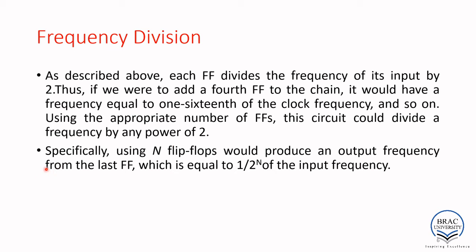Specifically, using n flip-flops, it will produce an output frequency from the last flip-flop equal to 1 over 2 to the power n of the input frequency. Okay, so input frequency divided by 2 to the power n. So it will give you the divided frequency.